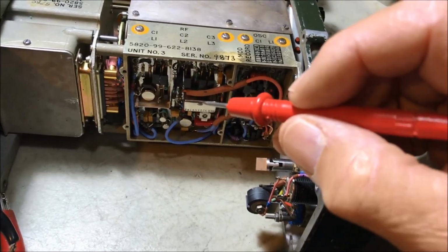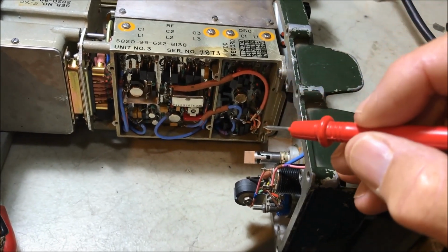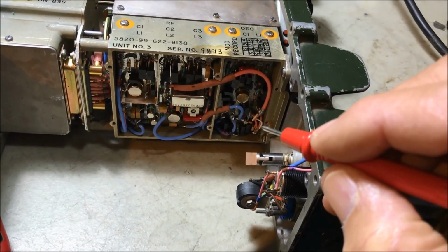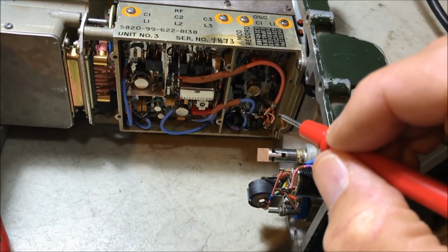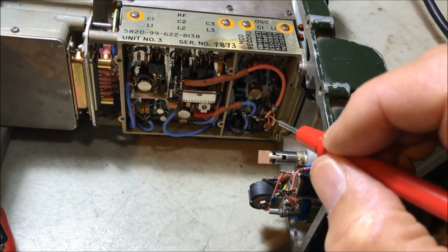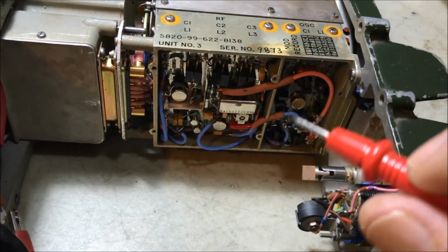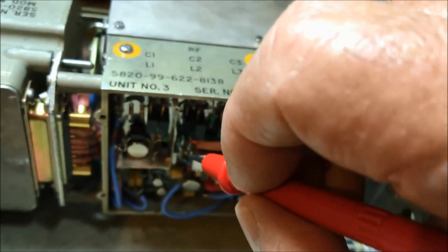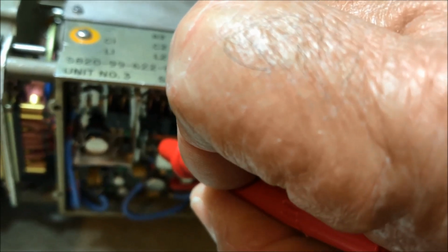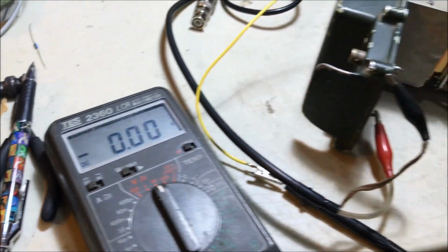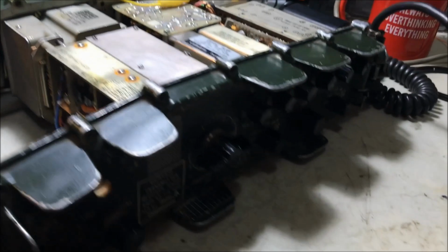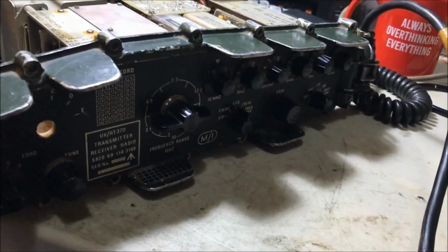Okay, so that's the DC supply cable that's going across. It comes up to the 3H board and then jumps across to the 3A board, and that's the difficult section there that I mentioned. I don't want to disconnect it there. So let's just go on to the point here on the 3A board and measure our DC supply. So I'm on there at the moment, and that happens to be 15.28 volts. So that's 15.28 volts for the frequency that's selected on the front dial. I think it's 14 megahertz or something.